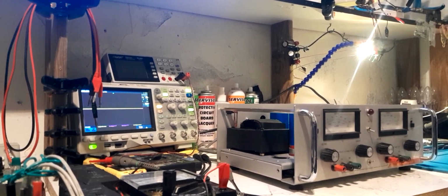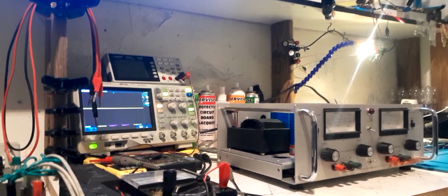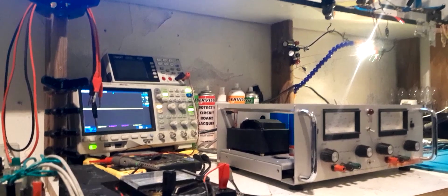So something I might end up doing is, after we have compensated everything and gotten rid of all the problems on it, I'll probably change those 10 nanofarads to 0.1s. I don't think I'll put 1s in there, because that actually could be high enough to cause a bit of a low frequency oscillation on startup between the transformer and the 1 microfarad caps on the op-amps.